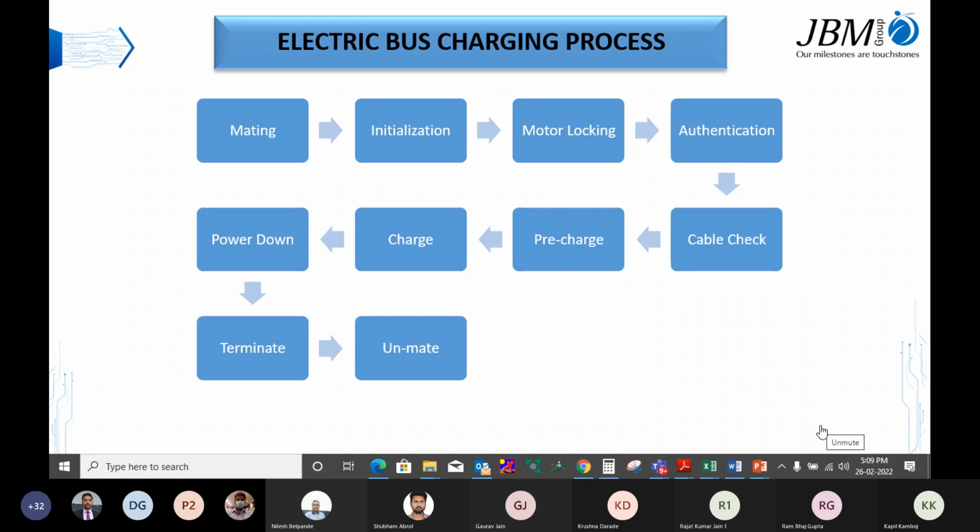The PP is changed to 1 to tell the EVCC that the gun is connected, and CP is the control pilot that makes the communication between the charger PLC and the EVCC. When the control pilot changes its CP duty, the EVCC locks the motor of the charging socket so that the gun cannot be removed during charging.